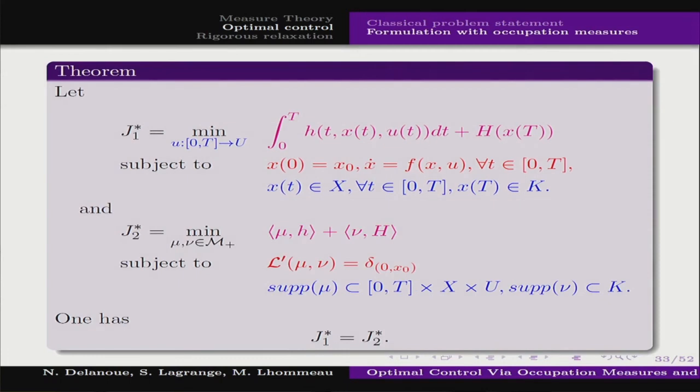And with the demonstration I've shown, it is possible to rewrite this nonlinear optimal control problem into a linear program. Let me explain. This integral with respect to t can be replaced by an integral with respect to x, but with respect to the measure mu, which satisfies this equation.